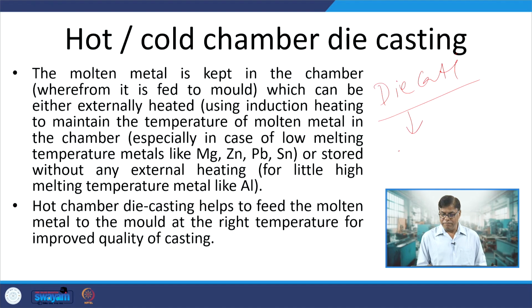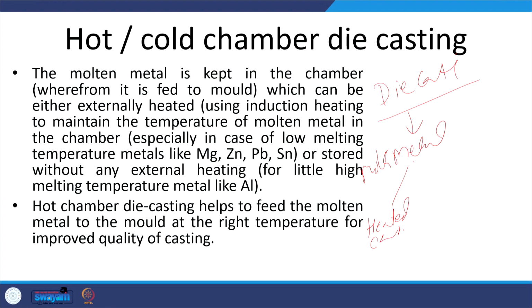One, where the molten metal fed from the ladle is heated continuously in the chamber, and from there it is fed to the die. Or there is no extra heating: from the ladle, molten metal is fed into the chamber and then pressurized to feed into the die for producing the casting. So, no external heating actually.